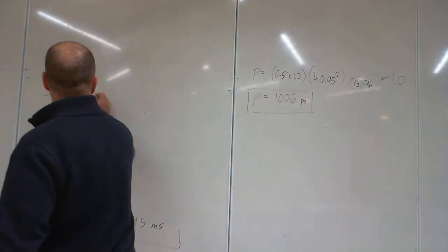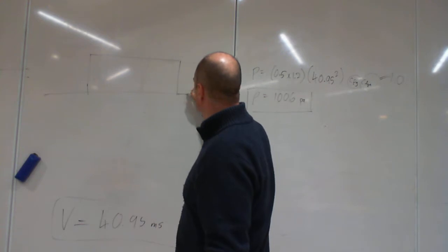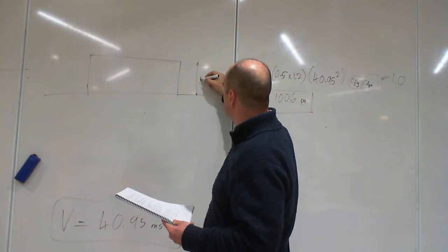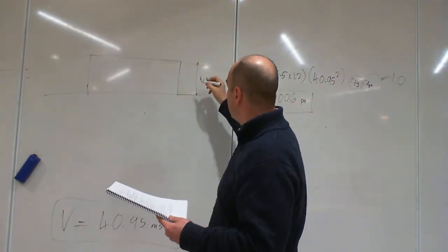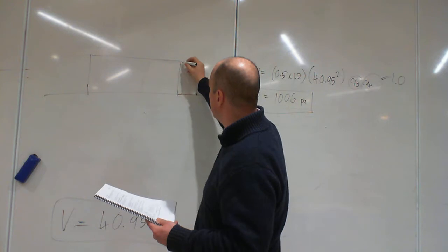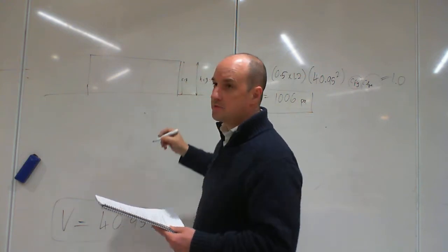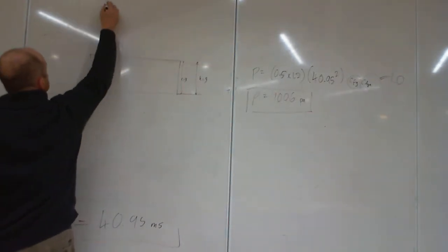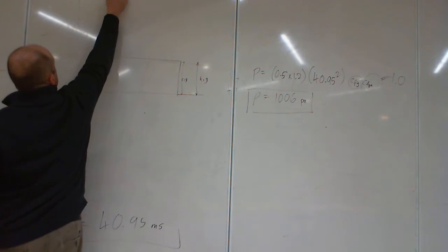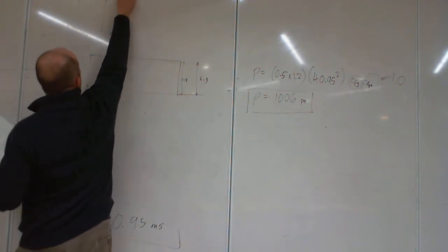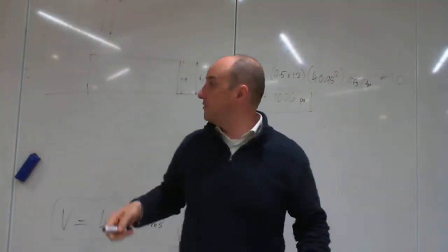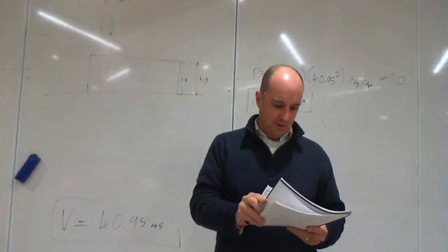So we draw our wall. Okay, a few dimensions on that. There's your wall, there's the H, which equals 3. There's also a value C, which is that value there. C is 3 as well. If this is a hoarding, there's the ground, and there's the sign way up there, okay? C is that height, and H is that height, so they're different. Where you have a wall which goes down to the ground, C and H are the same thing. We'll come to that in a minute.